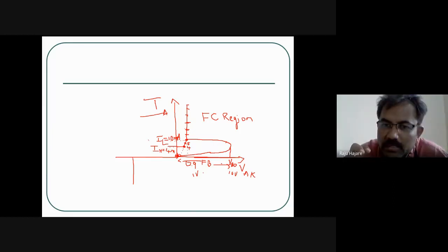In old regulators you will find a rheostatic, that is a resistive control mechanism, where you are varying the resistance value and thereby the voltage going to the fan. Inside the fan, what is there? An AC motor, correct? That AC motor speed can be controlled by varying the resistance. That was the old method. Today you will find SCR based, triac based regulators.